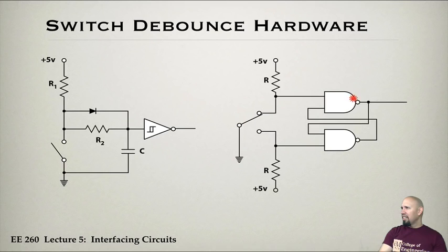Then you have this NAND logic. It's a little tricky to follow. Each of these has its advantages and disadvantages. Some work well, some not so well, and a lot of it depends on how rough that bouncing is. If the bouncing is simple, then most of these will work well. If the bouncing is really complicated, it may be difficult. So these are hardware switch debouncers. We can also have software switch debouncing, which you have already seen somewhat in some of the examples, homework, and so forth.